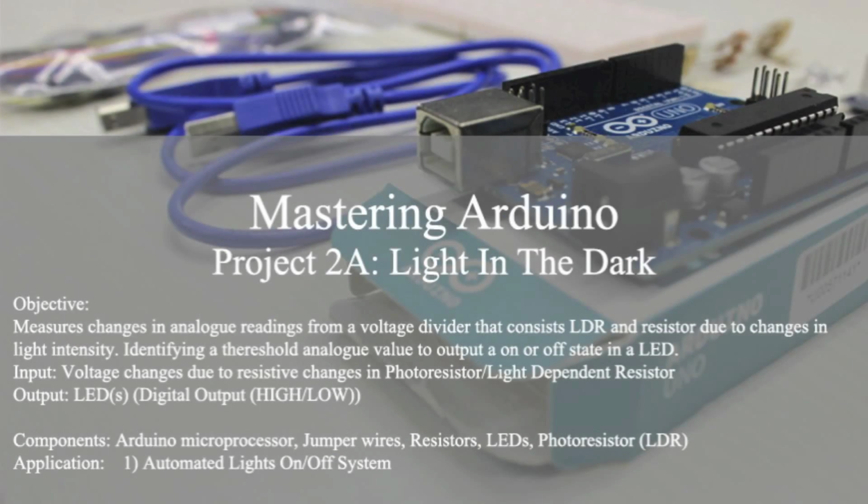Project 2A. Here, you will be using a photoresistor whose resistance decreases with increasing light intensity to create an automated lighting in the dark device. This is a very simple but applicable tutorial. We will be using inputs from a changing voltage in a voltage divider setup using a photoresistor and a 100 ohm resistor. The voltage changes in different light intensities because of the photoresistor. The output will be a simple LED.